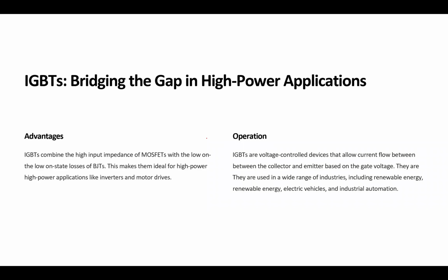When you talk about MOSFETs, I don't know if you get deep into them or not, but when you want to model the MOSFET, the semiconductor device, with an equivalent circuit, you have a certain amount of impedance at the input of the MOSFET that models the switch, and a certain amount of impedance at the output.